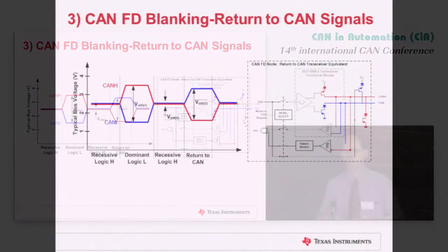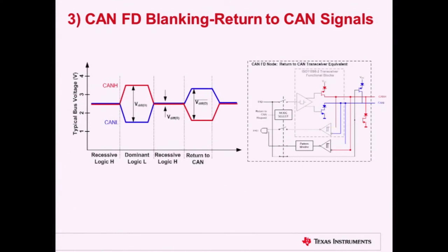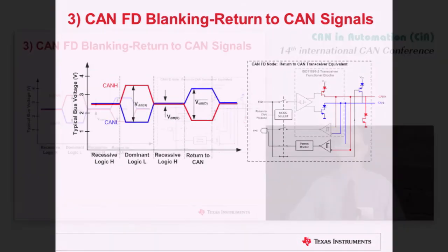So the next part of the question is, how do we actually get this inverted CAN signal out onto the CAN bus? So for the CAN FD side, we need to introduce a way to get a new inverted dominant signal or a differential signal onto the bus. So the first concept that we think about is fairly simple. We know the CAN driver. We can simply add one on that is inverted to the one we know.